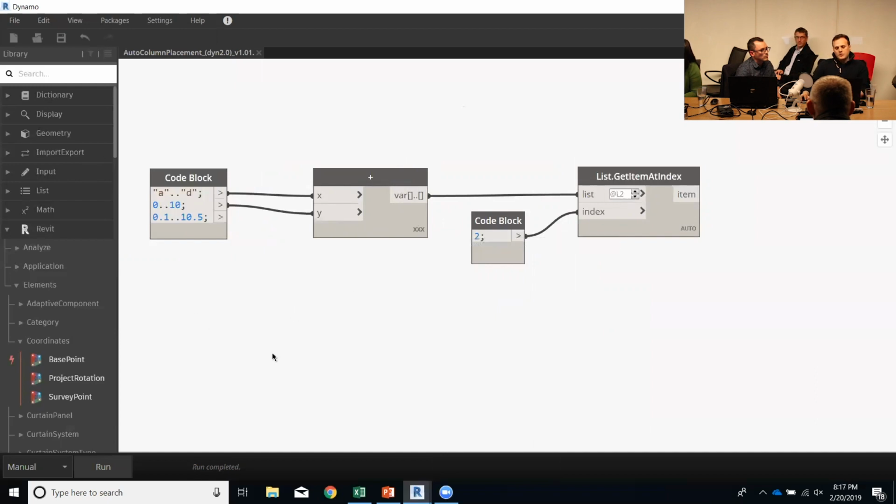In Dynamo, you have the ability to create what's referred to as a code block. And we can articulate things differently versus a string by identifying its quotations before and after. Or in the case of what we're seeing up here, an integer, which is something like a 0 item, or a float, which is introduced as like a 1.5, right?